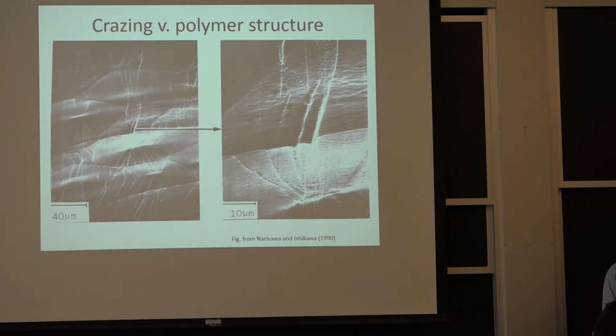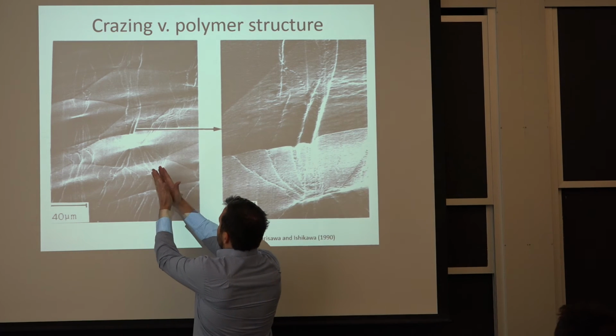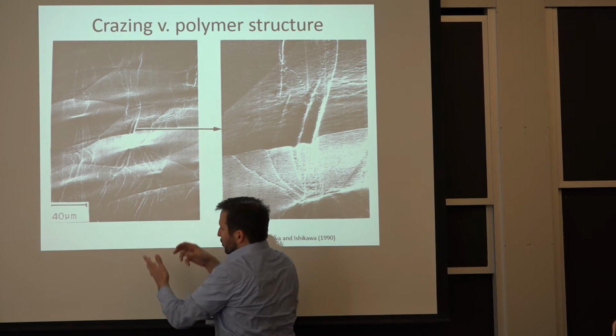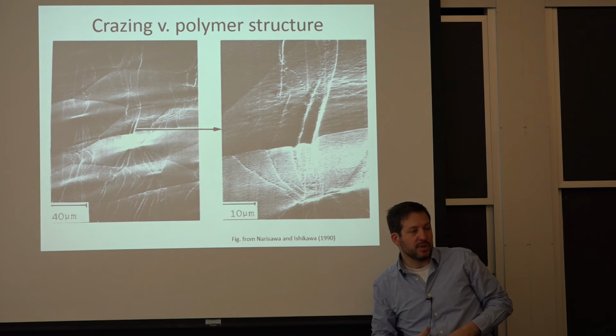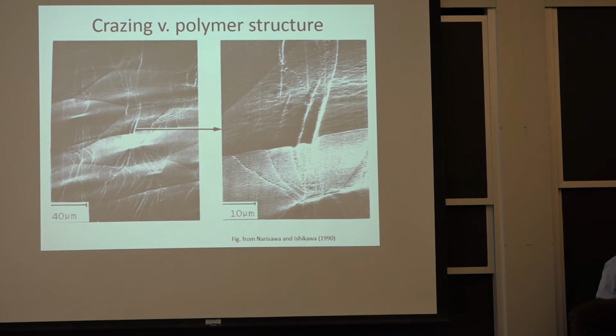So now that may make more sense, right? You have these crystals, and the parts that are oriented this way, when you spread, you get a little bit of hydrostatic tension between them in the amorphous zone. And because essentially the crystals are stiffer, they don't contract as easily, and that's where you can have the formation of these crazes.